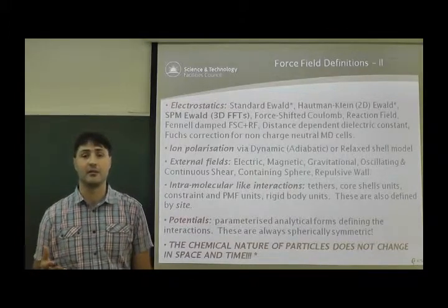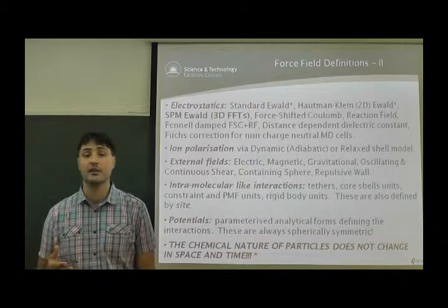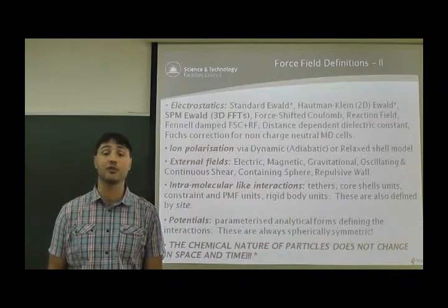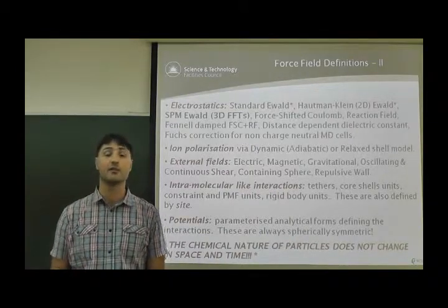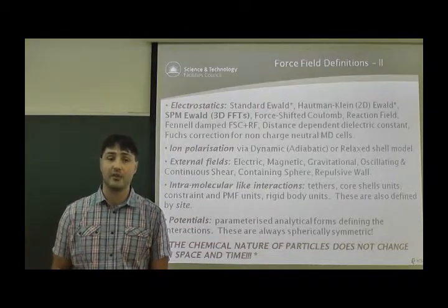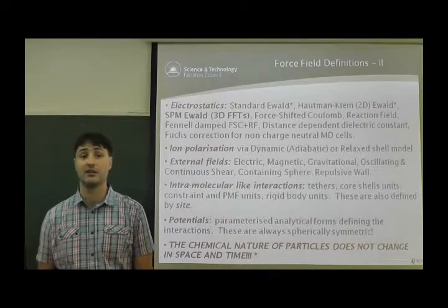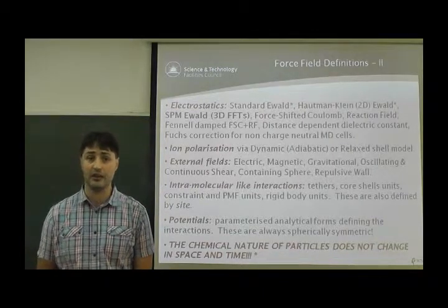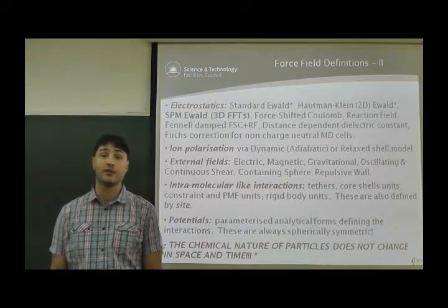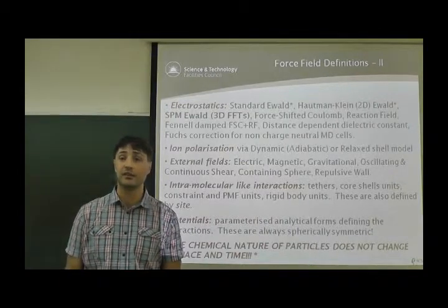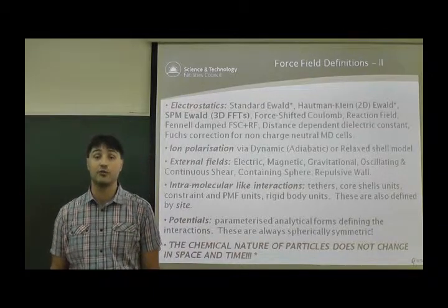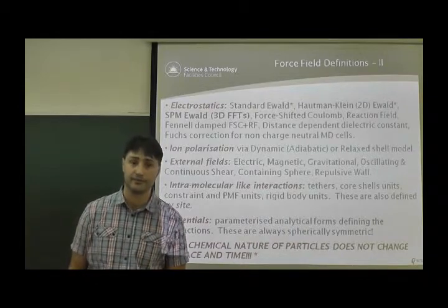There are various methods within DL_POLY packages. We have standard Ewald, or Hautman-Klein Ewald, which is aperiodic in one direction for slab simulations. These are only available within DL_POLY Classic. We also have SPME, smooth particle mesh Ewald, which relies on 3D FFTs for the correct Ewald summation. And we have some approximations, such as force-shifted Coulomb, reaction fields, damped reaction fields, distance-dependent dielectric, and we may account for non-charge-neutral MD cells by using the Fuchs correction.